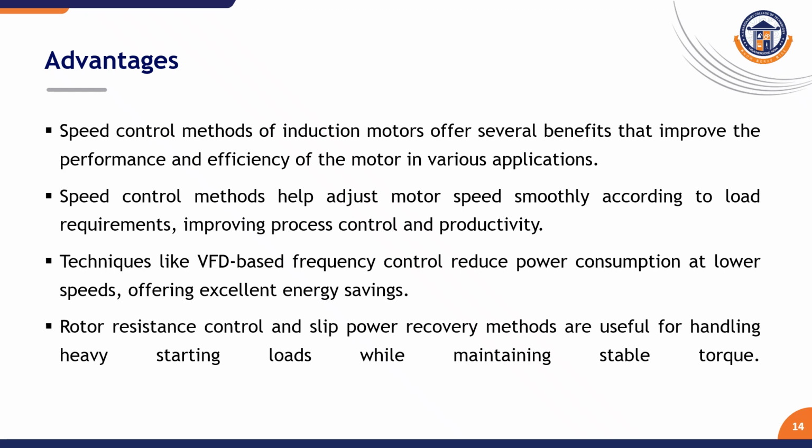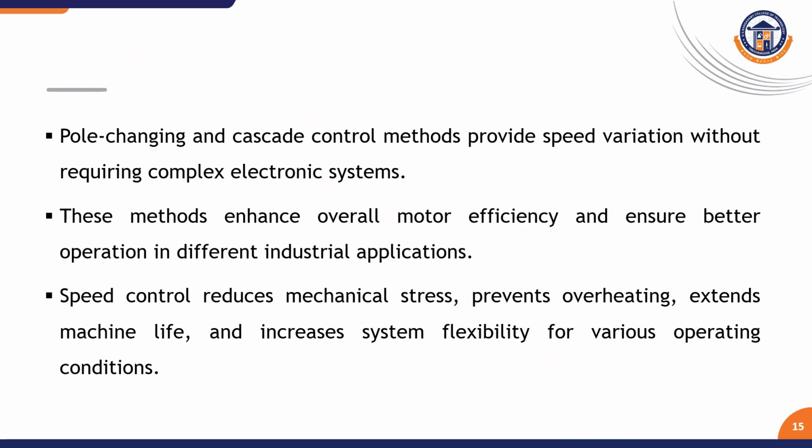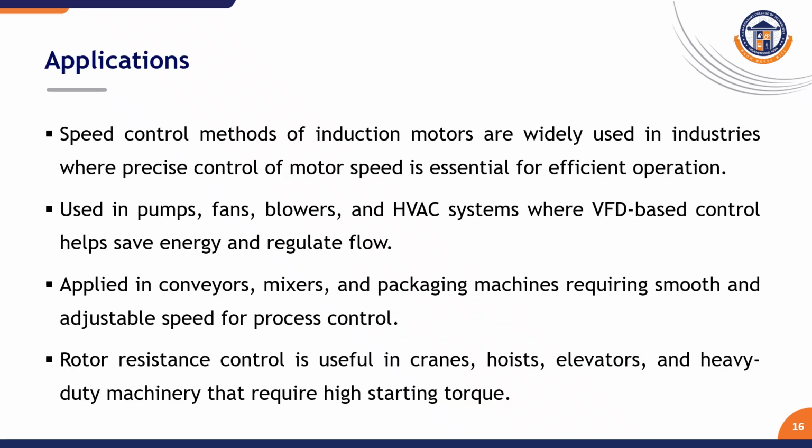Next, advantages of speed control. Speed control offers several benefits by improving the performance and efficiency of the motors in various applications. Techniques like variable frequency drive based frequency control reduce the power consumption, and rotor and slip power recovery schemes can be used for heavy starting loads. Pole changing and cascade control methods can provide a speed variation without complex electronic circuits. Speed control reduces mechanical stress and prevents overheating, extends a machine's life, and increases the flexibility of various applications with different operating conditions.